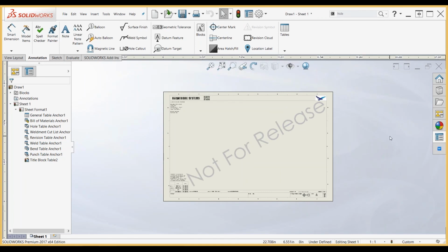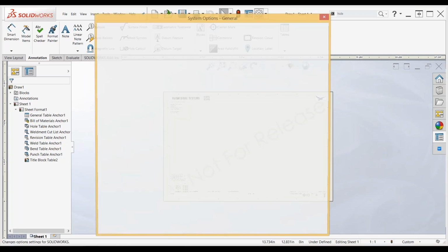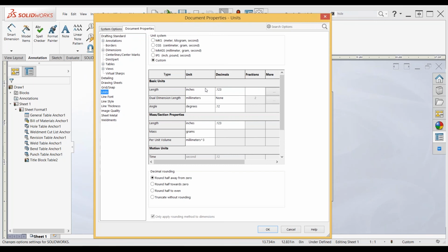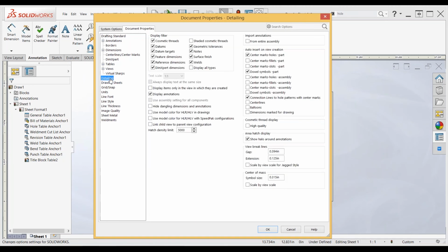So saving them from having to zoom in, because maybe they're not too familiar with SolidWorks, they have the zooms all backwards, they do it different than you. I'm just going to save a view to kind of snap to this location very easily. So bringing up my orientation tools by just hitting the spacebar button, you have the ability to add a new view. And I'm going to give that new view a name, and I'm going to call this title block.